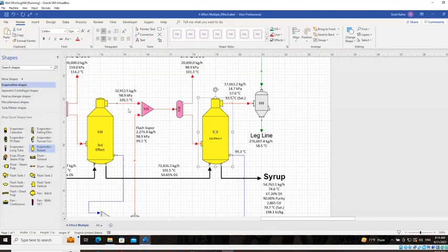No, I asked the question, actually. The temperature gradient is one of the most important parameters for evaporator. And I expected it should be shown in the legend. It is a difference between the temperature of heating steam inlet evaporator and juice outlet evaporator. But unfortunately, it is not listed in the legend.